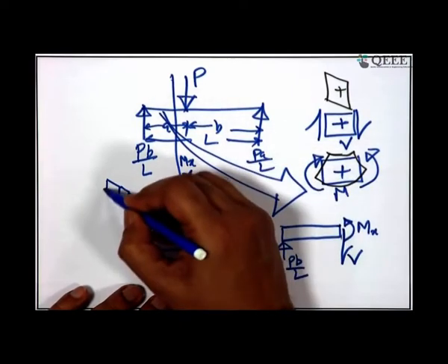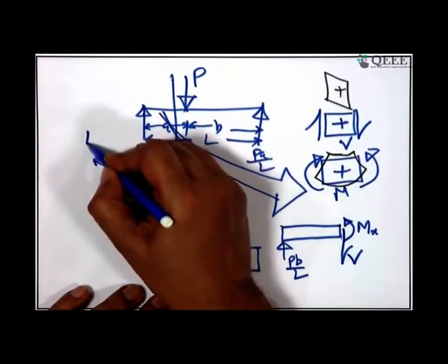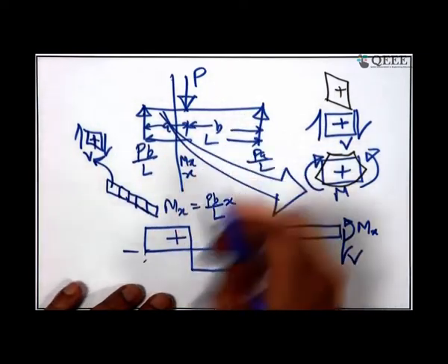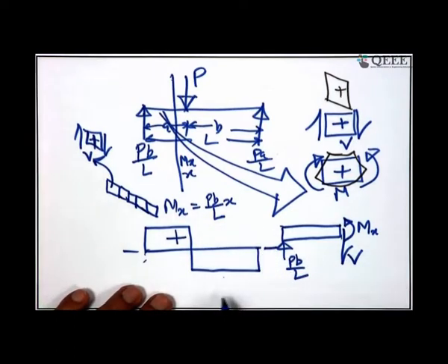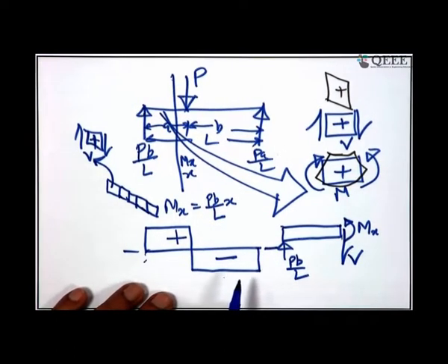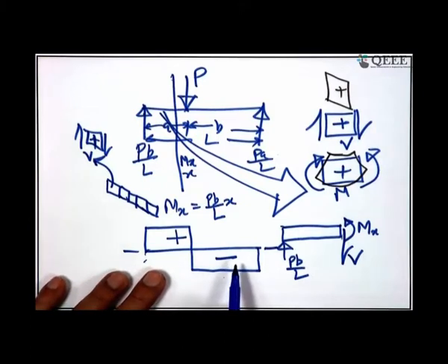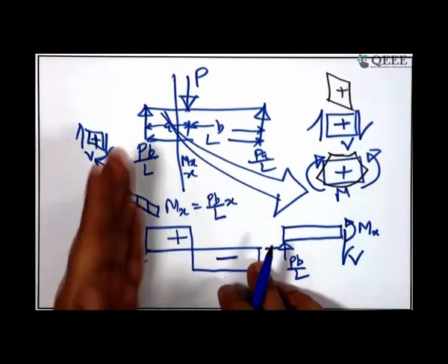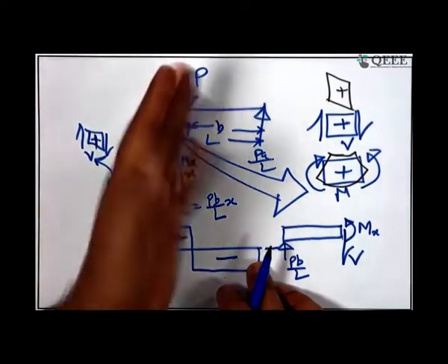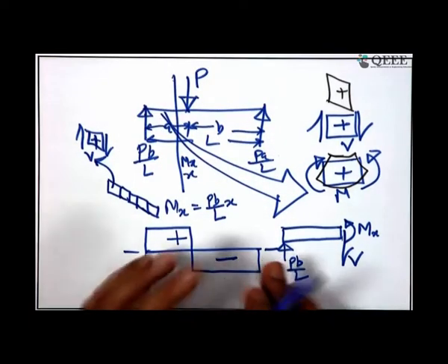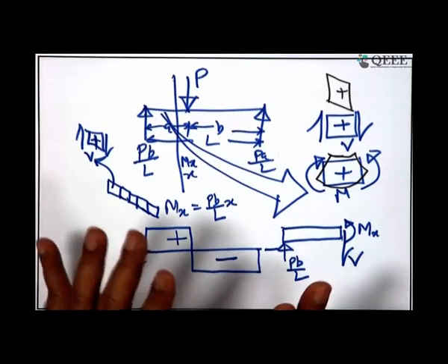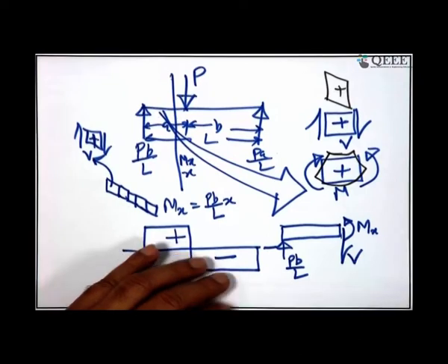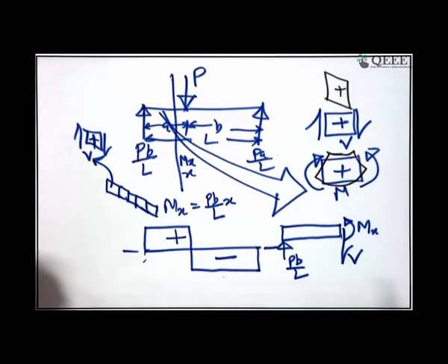So, I say that if I isolate one of the members, it will actually be left up, right down, positive shear. If I take this positive, then it becomes very easy for students to visualize and quickly draw the shear force diagrams, and it is very intuitive and very natural. I am having a force, I am drawing it. So, basically what you are doing is drawing the external force itself and calling it an internal stress resultant.